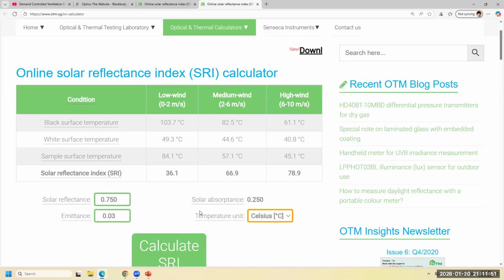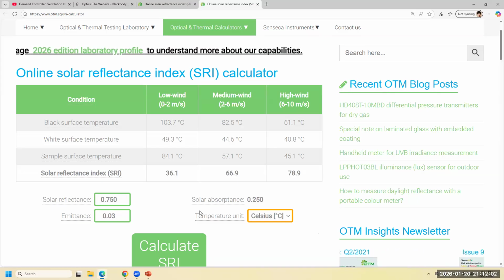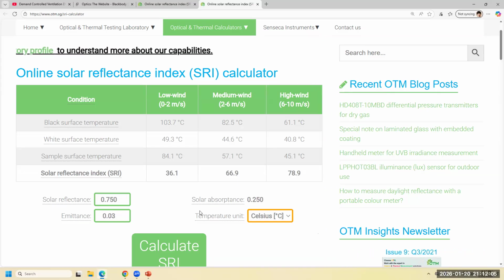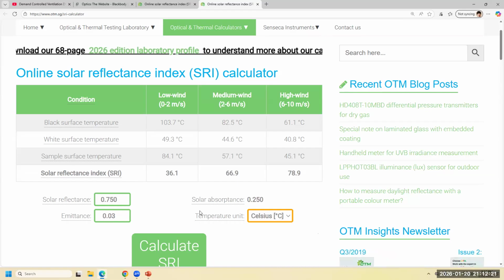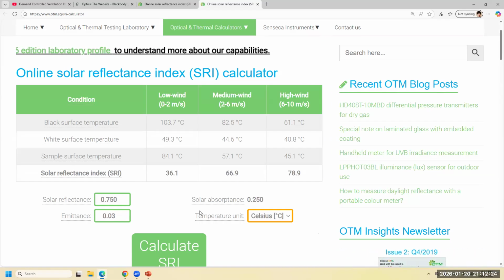If a city has cooler surfaces and hotter surfaces, there will be another story, because it accelerates the urban heat island effect. Not only the heat rejected from our air conditioning systems, our cars, and our energy utilization processes, because all losses become heat, but also, in nature, we don't make good use of solar energy and the cold universe. So that causes the urban heat island effect and high building energy use as well.